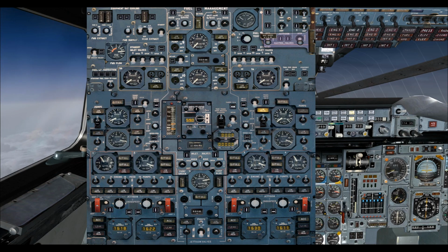And there we are at 59%, so we can close up our trim transfer. I also quickly just want to mention something about the interconnect valves between tanks 5 and 8 and tanks 6 and 7. These can be used to balance out the sides. It's not the preferred method because it's slow, so it has to be monitored a lot more closely, but it is available if you want to use that method.